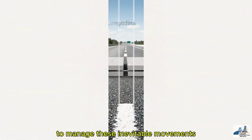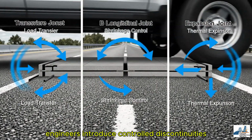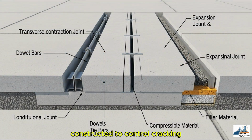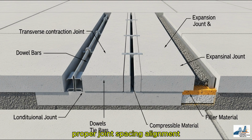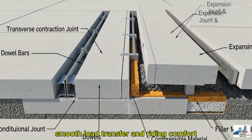To manage these inevitable movements, engineers introduce controlled discontinuities. Joints are intentionally constructed to control cracking and accommodate thermal expansion and contraction. Proper joint spacing, alignment, and detailing are essential to maintain smooth load transfer and riding comfort.